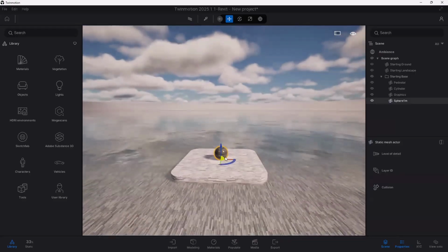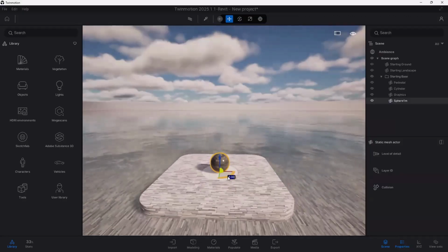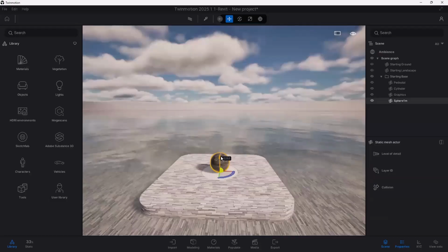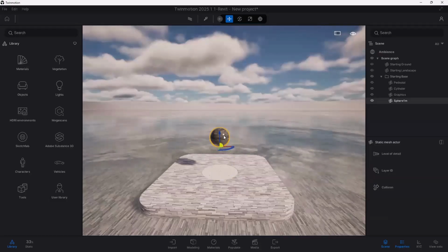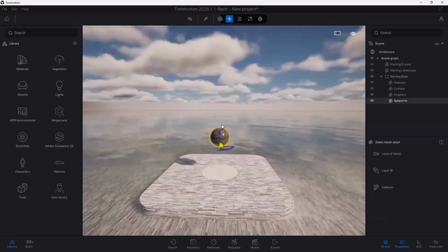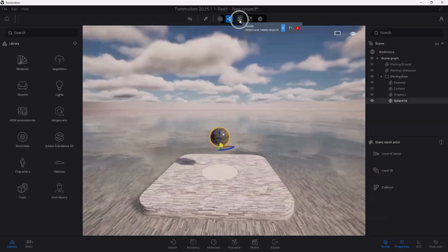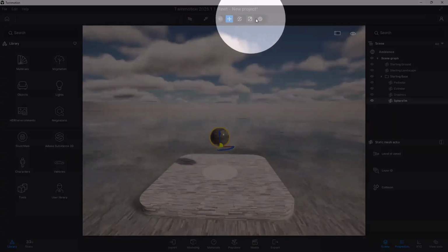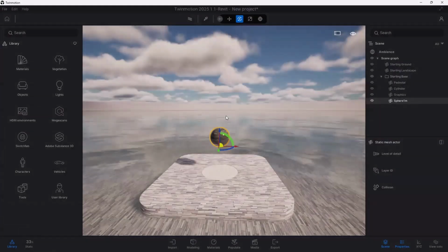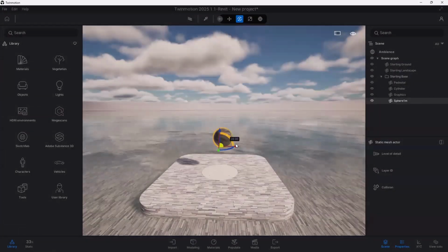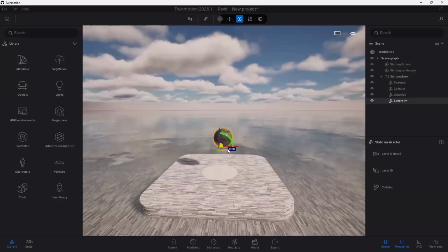But when you select an object and you want to change it, you'll see that there are controls here that you can grab. So I'm rotating the object. I can also grab this and drag it up and type in a value. If you don't want to move and you instead want to purely rotate, up the top here are the actions on an object. So I can click here and do a bit of an earth rotation, and then start spinning it around. This gives me 3D rotation.